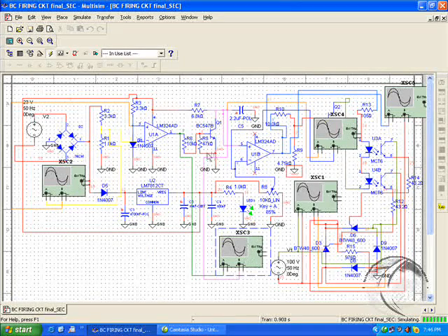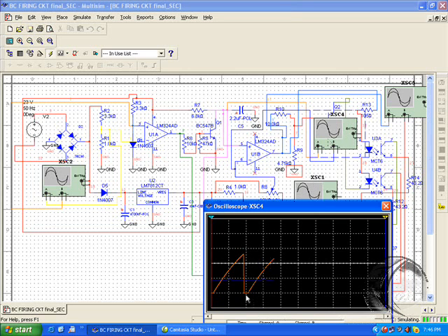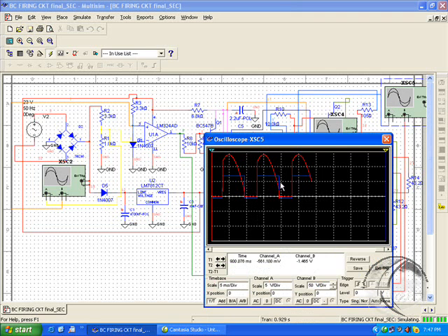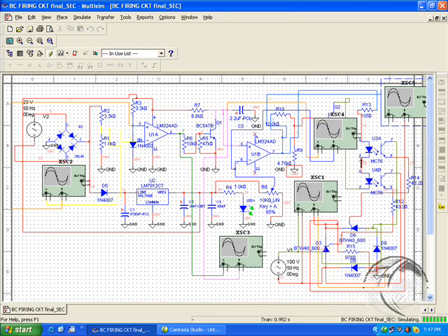And after that zero cross detection, it is being fed to the transistor, and there is a capacitor here with charging and discharging taking place. And that charging and discharging takes place by this, and then we have the output LED which is fed this much of on time and this much of off time, and those two LEDs are connected in series, and ultimately they are feeding two SCRs and two diodes which are in the bridge configuration, being fed from AC supply. And that is how it works.